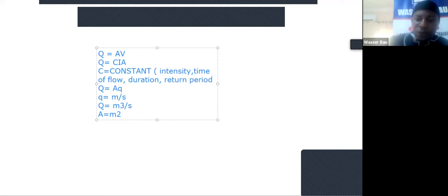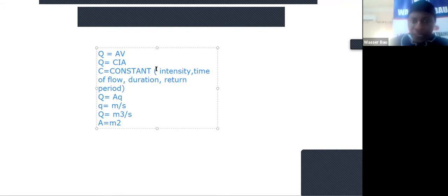There's an intensity of rain that fell in Abuja recently. I told those people that the rain is a 10-year flood, because that estate is always flooded every 5 years. So as a water expert, I told them, look, this is going to keep happening because the drain system in that area is not designed to accommodate more than a 10-year return period flood. So when a 10-year return period flood comes, it carries houses, it carries things.